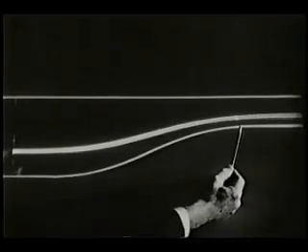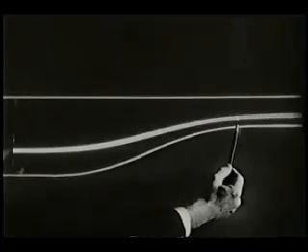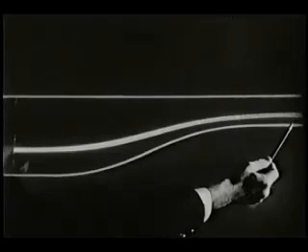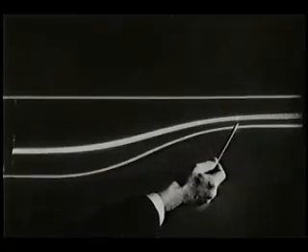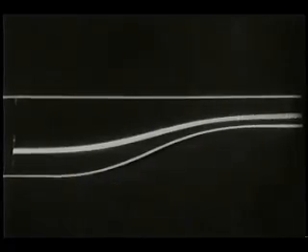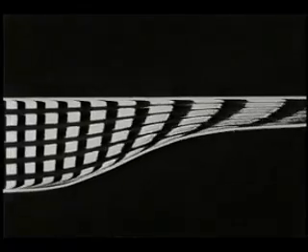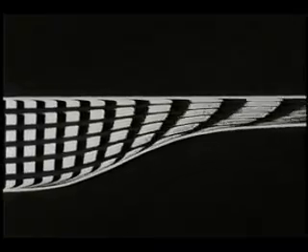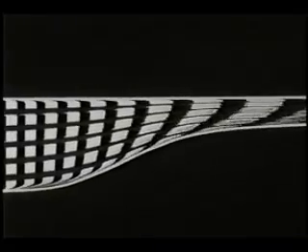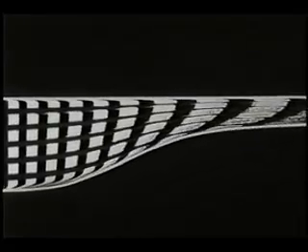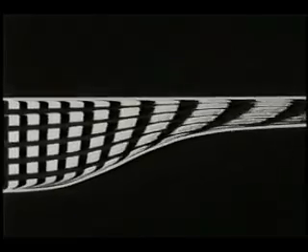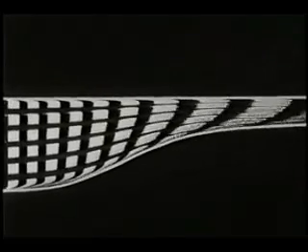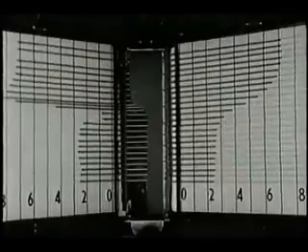Where the pressure rises on the curved wall, the viscous boundary layer thickens. If a rising pressure gradient is severe enough, the boundary layer might separate, or a laminar layer might become turbulent. To minimize adverse pressure gradients in wind tunnel nozzles, the contraction is made more gentle, as here.